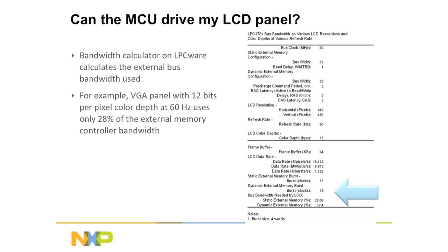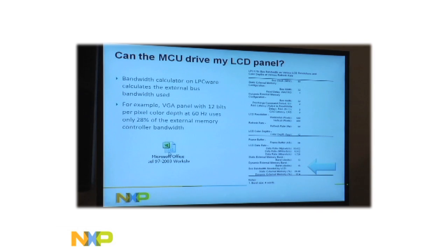So one of the interesting support areas that you can access for the 4300 itself is at lpcware.com. It has a lot of the software drivers and demos that are available to support this chip. And one key utility that you can download from there is what they call a bus load calculator. For example, you're using these graphics. You know what the color depth is going to be, right? What your resolution is going to be. You just input these key parameters into the spreadsheet, and let me see if this works here.